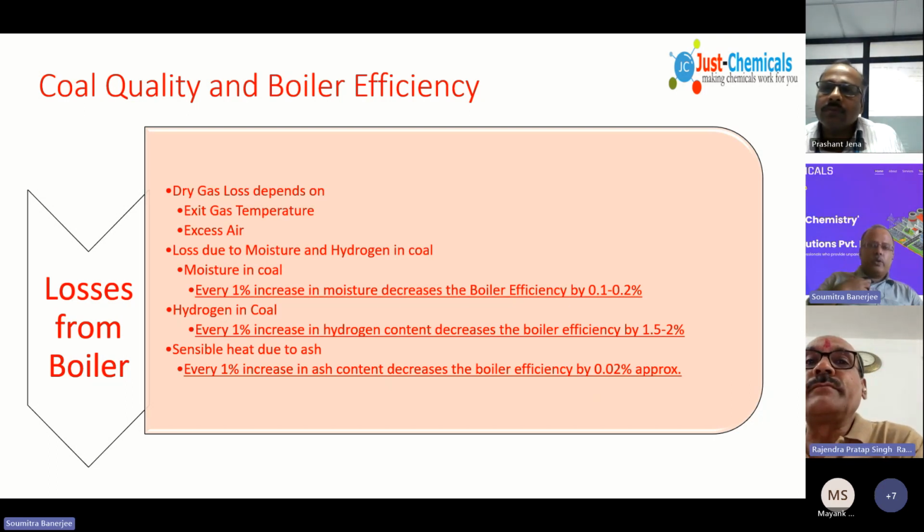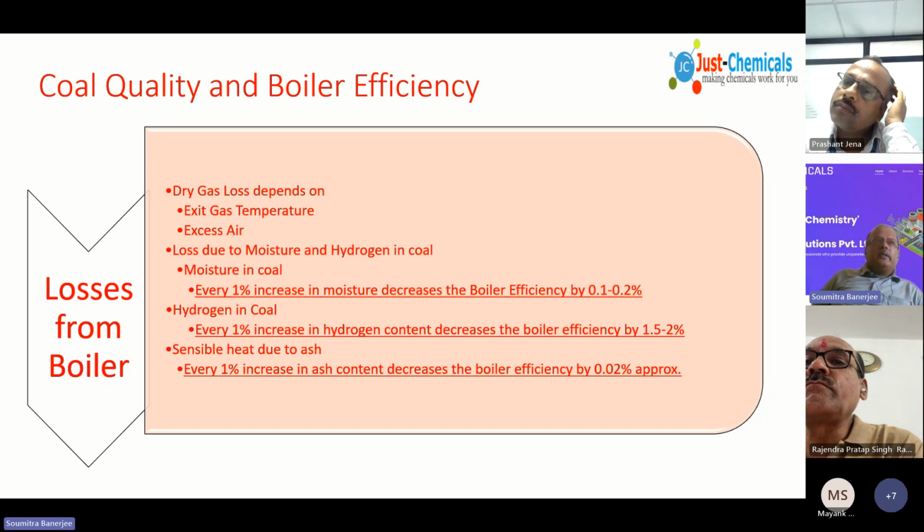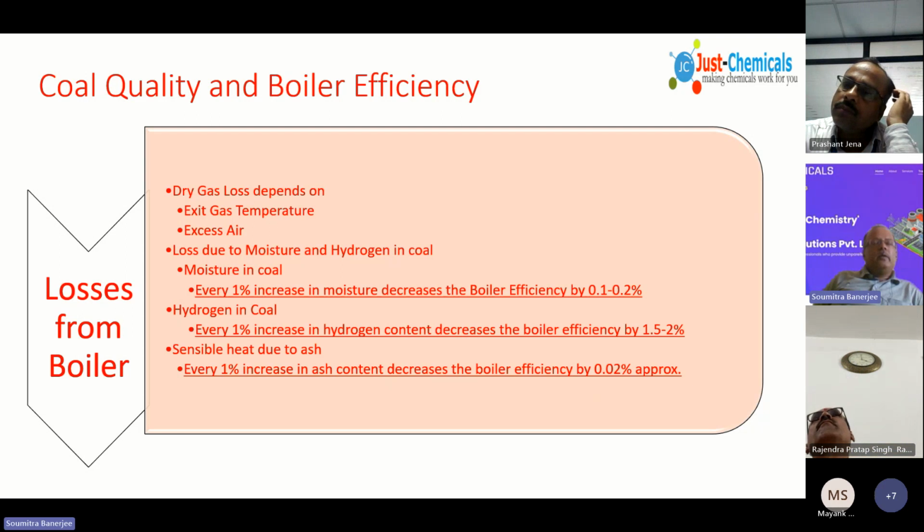572 megajoules it is producing, but for the H2O which it is producing, if you take the enthalpy of H2O at that temperature, of saturated steam, and multiply by the saturated steam, you'll find that the heat generated due to hydrogen is still higher than the loss due to the latent heat of evaporation which it has carried.